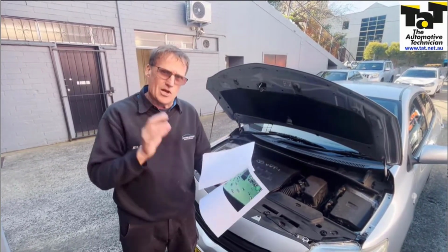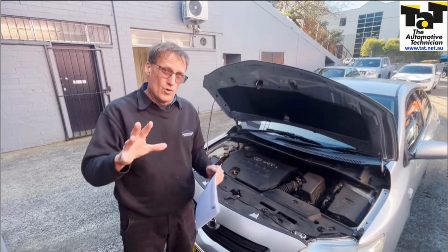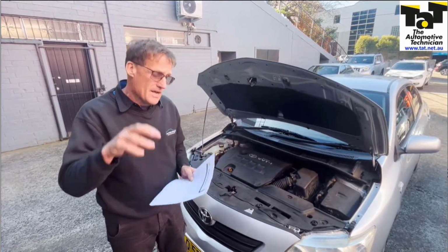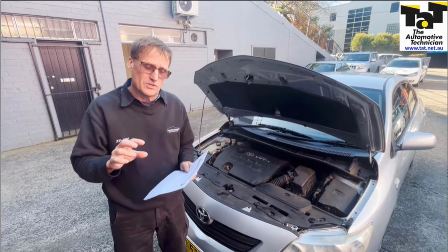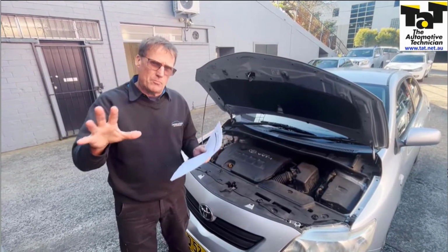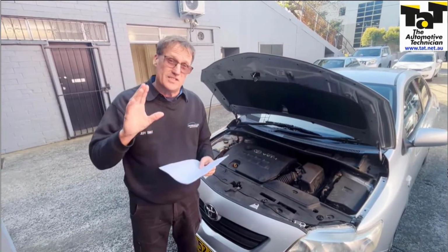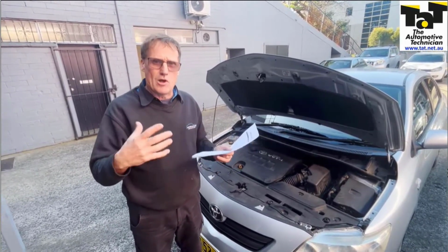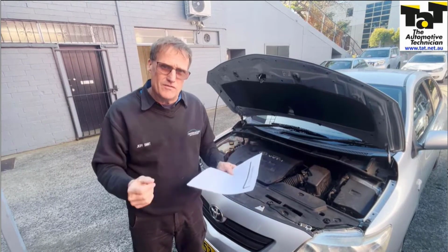But again, you can desolder and resolder those relays on there, either 40 amp or you can even go to a 70 amp relay, which is a bit of a modification on the pins, but you can make them fit into that printed circuit board. So if you want to repair it yourself, that saves any programming issues, because guys have refitted second-hand ones with literally the same part number, but then they've got some hard fault codes in there in regards to compatibility of that unit in the car.